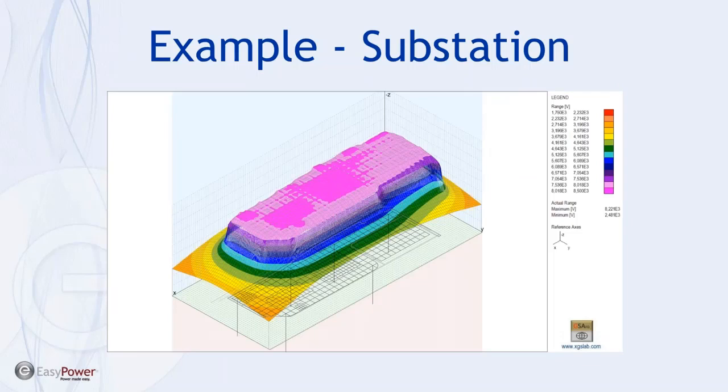This visual shows the ground potential rise with the proposed grid design. This is during the design fault that we've applied, in the soil model, with the preliminary grid design shown below. You can see the grid and some ground rods going down in the Z direction from the grid. This is a nice visual because you can see that the grid area, the elevated area in pink on the GPR chart, is brought together up onto an equipotential plane.